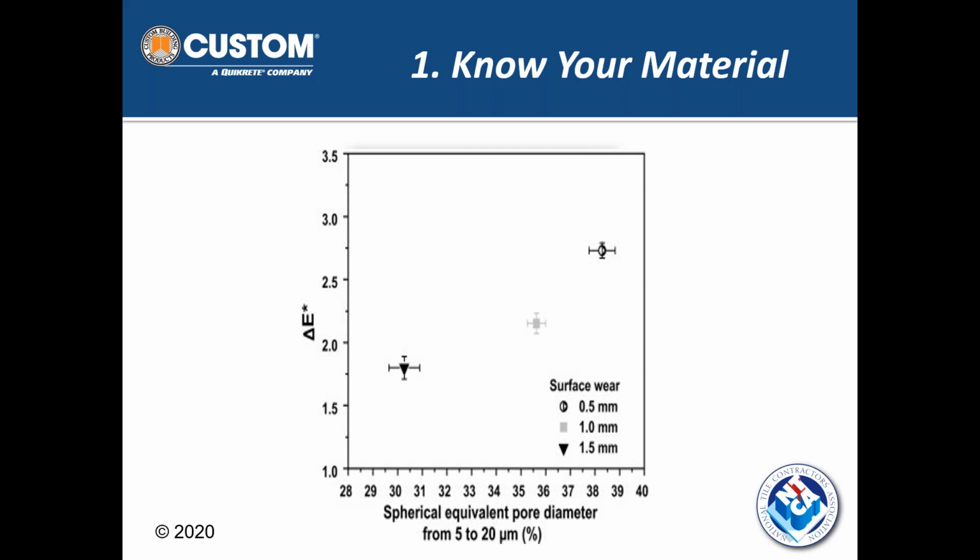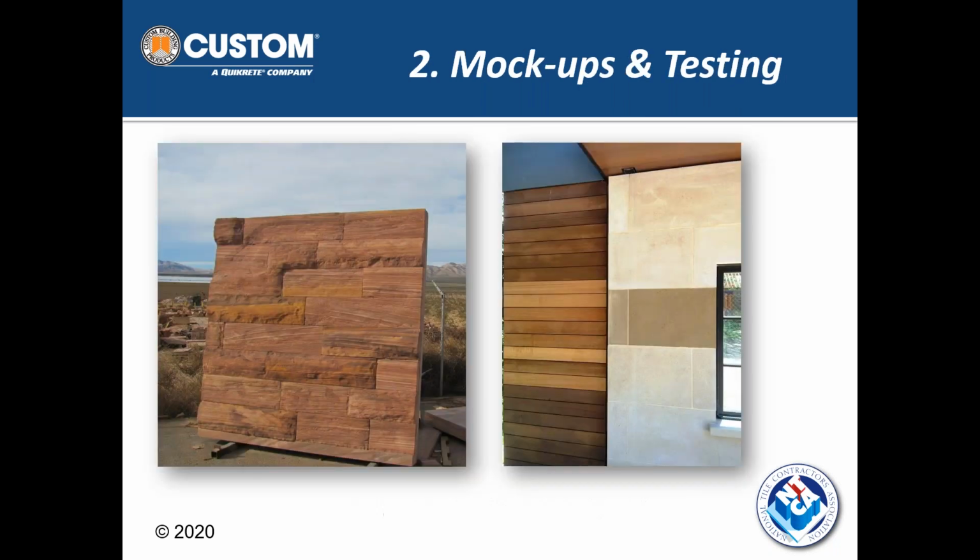So again, without going too technical, hopefully that makes sense, but that's why it's important to understand that this is not good or bad material or good or bad manufacturing. This is just explaining why you may or may not have had issues in the future if you just assume that you should never seal unglazed porcelain or that you should always have to seal unglazed porcelain. So if you have to, great, but I'm also a believer that if you don't have to seal it, I would absolutely agree with that. Save time, save money, don't seal it. Don't use a grout release. But unless you know that answer, again, it's important to understand and vet that out for yourself.